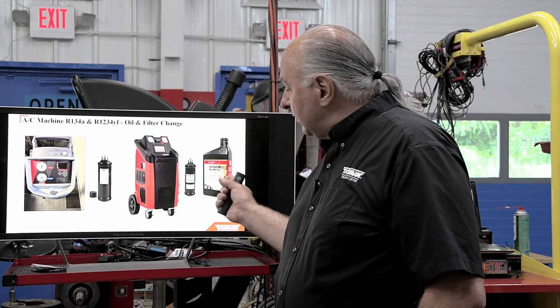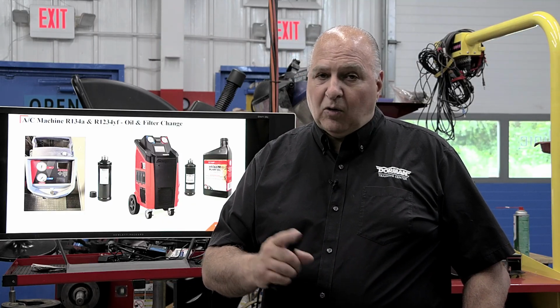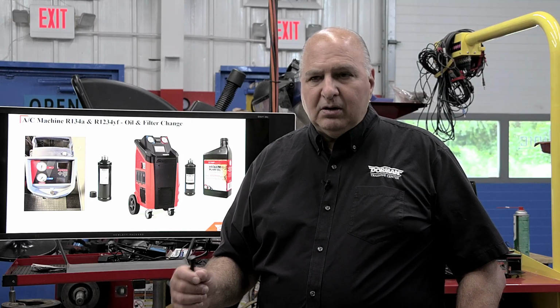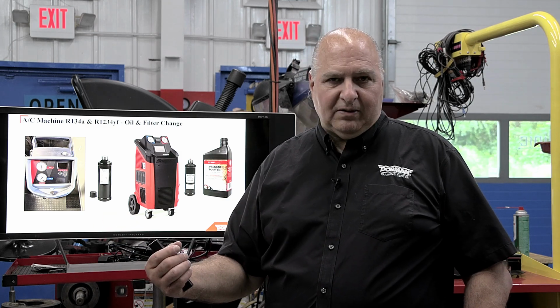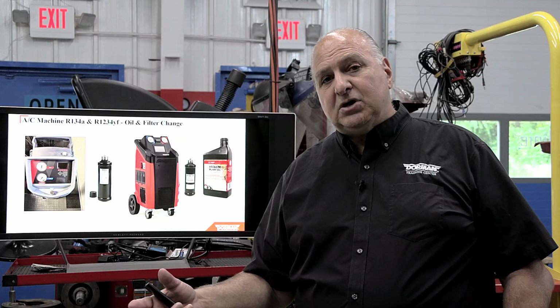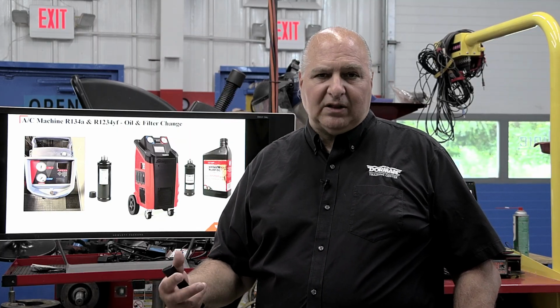And once that bottle is open, you use it once. It's hygroscopic, meaning you use it once, not all of it's going to go in the machine. What we do is open the drain, drain it out, pour some new in to get some of the dirty oil out of it, close it up, fill it to the line or whatever the manufacturer suggests, and then run it to make sure you're at the right level.